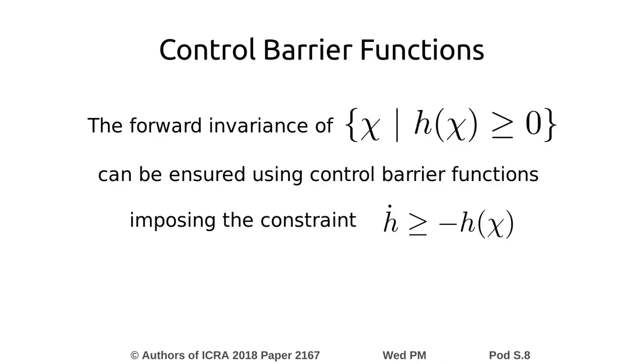At this point, we can leverage a nonlinear control technique known as control barrier functions to render this set forward invariant. Control barrier functions provide an inequality constraint that, if satisfied, allows the robot to never run out of battery and to continuously execute the given task. In particular, if the robot model is affine, this constraint is an affine constraint in the robot input.